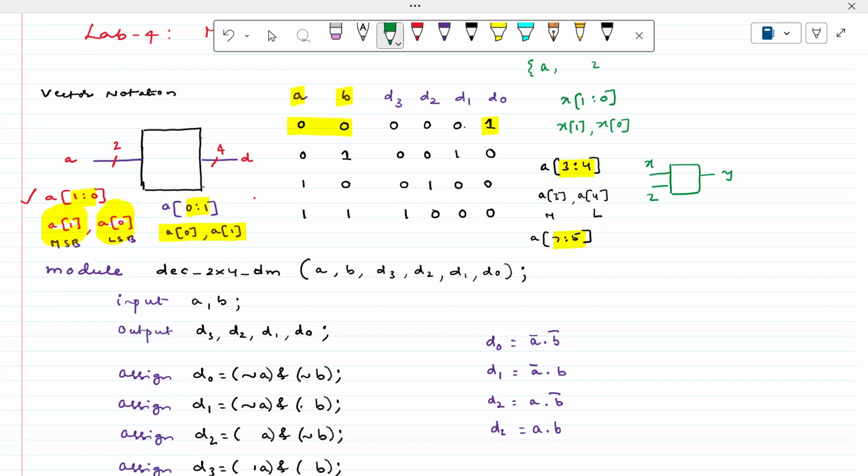But unfortunately, in Verilog we are going to use x and z for value purposes also, along with 0 and 1. If you use capital X and capital Z, it is not a problem, because Verilog is case sensitive. Definitely 0 and 1 and the small x and small z are meant for values. But never try to use x and z for variable declarations. Okay, my recommendation